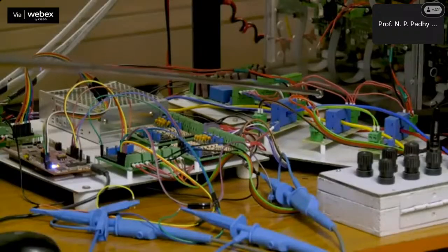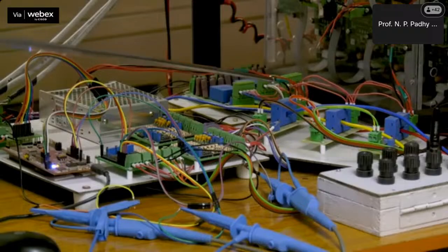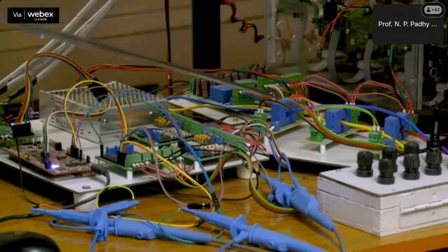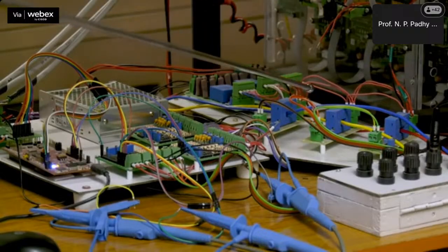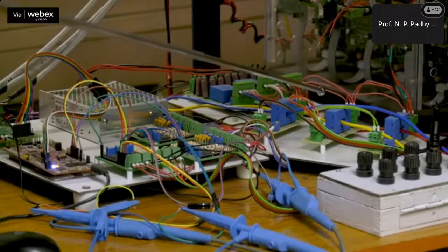We have used Hall effect based sensors for both voltage and current sensing. A LEM make voltage transducer LV25P is used for voltage sensing, while the current transducer LA55P is used for current measurement. Apart from these LEM sensors, the voltage and current measurement sensor circuit also consists of signal conditioning circuits and level shifting circuits.